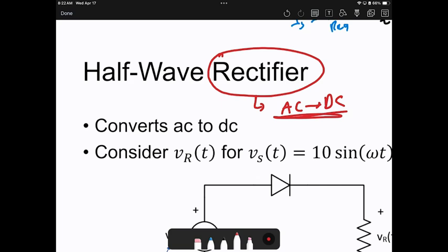Even the cell phone is DC; wherever there is a battery, it's DC. The charger actually converts AC to DC and does some control on the voltages as well. So we need to convert AC to DC by using a rectifier. You can find rectifiers in most chargers. Then after we convert AC to DC, there is another part of control to make it the same voltage level, which is 5 volts, etc.